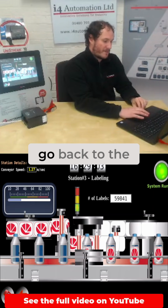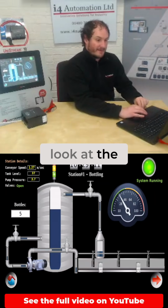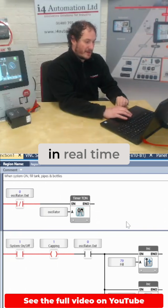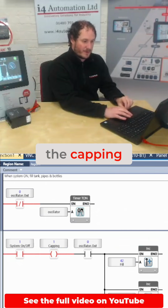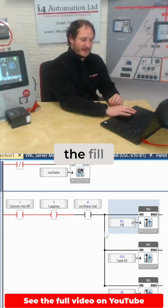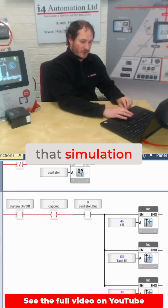So if we just go back to the actual bottling part of the PLC, we can go straight in and have a look at the UniLogic software again. And as I said before, we can see this in real time. We've turned the system on with the button on the HMI, and that's instantly connected the capping coil. So the capping is now on. And as we can see, what that's doing is just simulating the fill of these bottles, which is filling up. When it gets to 100, it's going back down again and starting up, just creating that simulation on the screen.